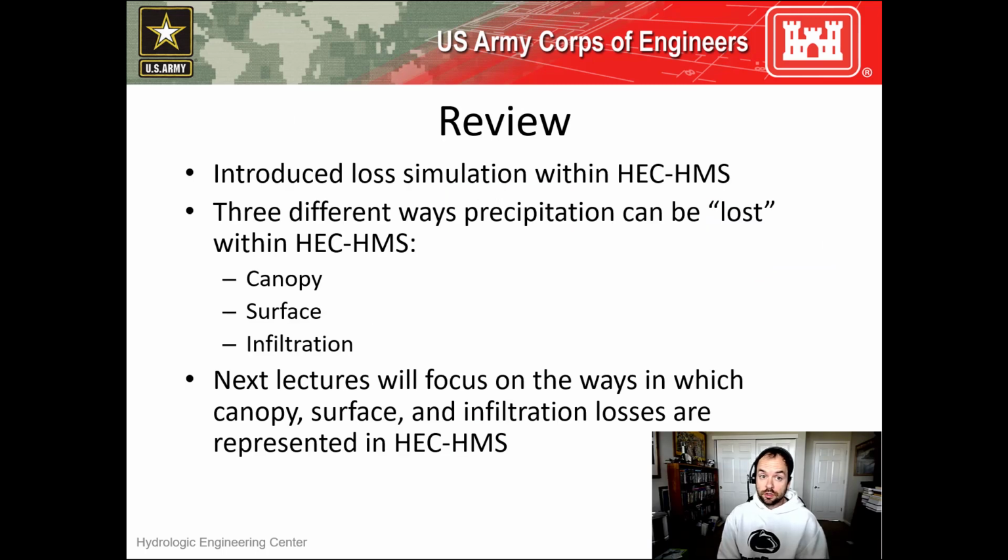So as a review, in this video, we introduced loss simulation within HMS. As we discussed, there are three ways that precipitation can be lost: due to the canopy, the surface, or through infiltration. In HMS, you have the option to simulate all of these processes, two of them, one of them, or none of them. Within the next two videos in the series, we're going to look more closely at how canopy, surface, and infiltration processes are simulated and go into a little bit more detail.